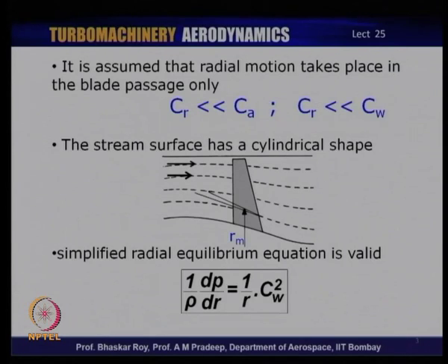The annular passage that goes through the turbine, depending on the turbine pressure drop or pressure ratio, would have to open up, and in the process of opening up, it creates a diverging passage as opposed to a converging passage in an axial flow compressor. And this diverging passage automatically promotes a certain amount of flow which is non-axial. That means it acquires a certain amount of three dimensionality.